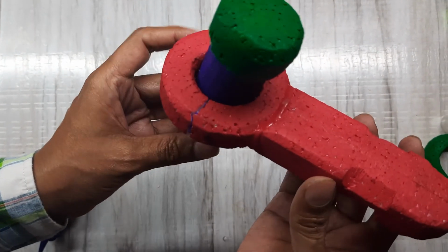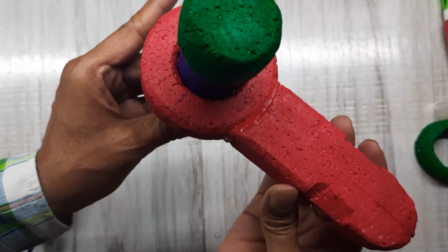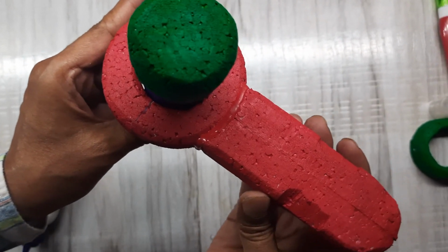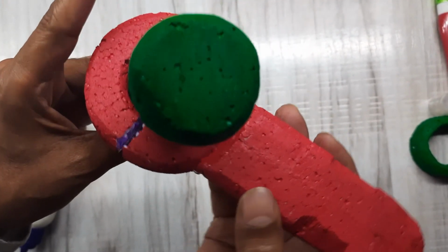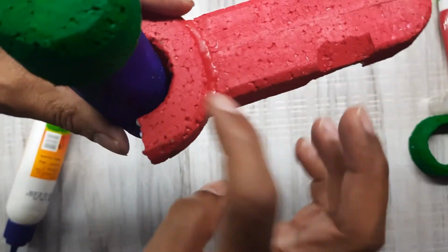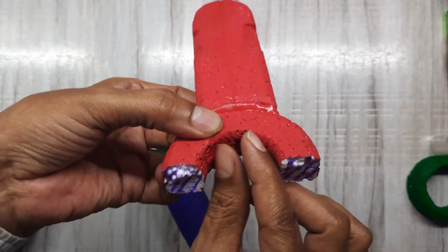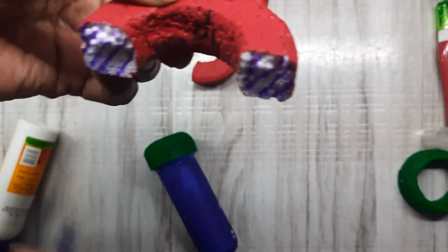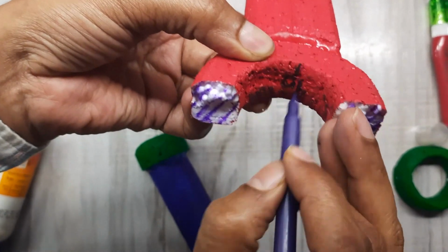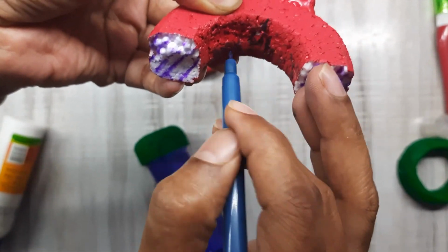See, naturally, when we insert the pin, there will be somewhat of an angular rotation, and the crushing action will take place between the single eye and the pin. At this region the crushing will take place. Here, this is the zone where the crushing will take place.